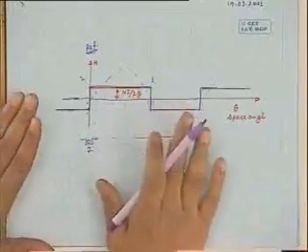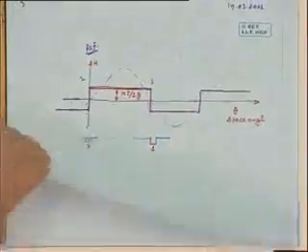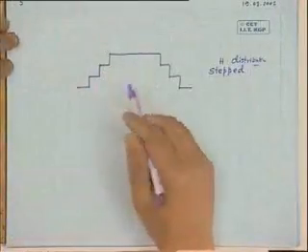We will see how the induced voltage because of different harmonics can be eliminated at a later stage by not using a full pitched coil. It can be shown that by not using a full pitched coil, you can eliminate some of those harmonics. Anyway, this is something worst, a single coil rectangular distribution.